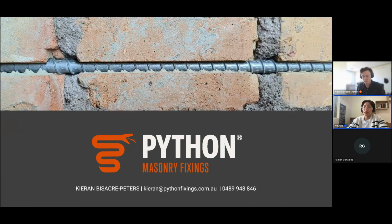We're down to the last question, again from Jesse. Without waiting for failure, how would you work out if all the epoxy anchors were installed correctly or were working properly? Good question. As engineers, our best tool for dealing with that is QA. Often in structural specifications in the past, I've seen 2 to 5% of anchors must be proof tested after install. That is a good way of addressing it. Probably the most common way is that a percentage of anchors are proof tested after install to check that the installation is sufficiently done.